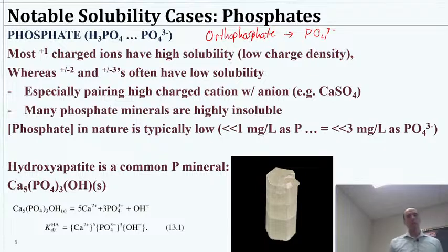That depends on the exact pKa, and I don't have those off the top of my head. But if you're adding orthophosphate, that's going to scavenge up some of the acidity and help buffer the system to keep it at that slightly elevated pH, which in general helps keep the minerals and metals in your system less soluble, so that keeps them on the pipes.